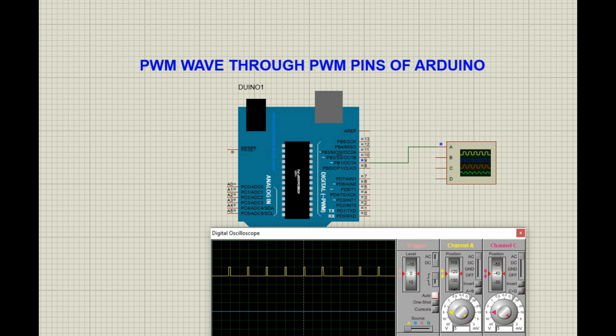As of now, we are making changes in the program to get the various values like 50, 10, 100. If we could attach a sensor at the input, like a potentiometer, from where we can get those values directly, then by moving the potentiometer we can change the width of the pulse, and that's going to be very useful for our upcoming experiment. So for that, we'll add a potentiometer at the input side of the Arduino. So let's see that.